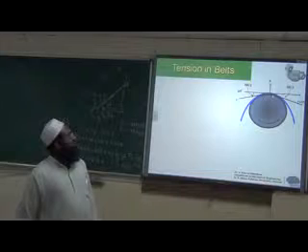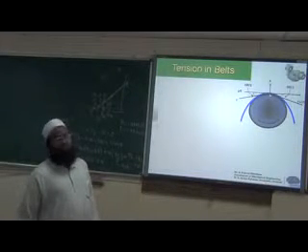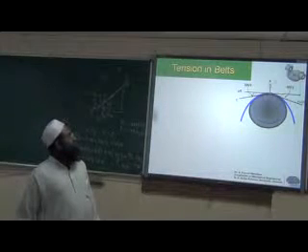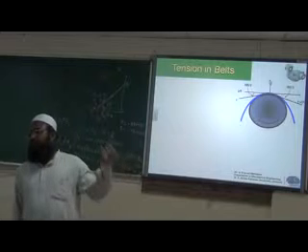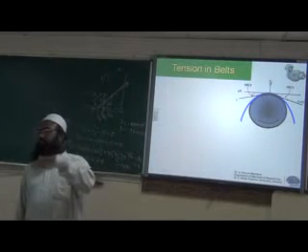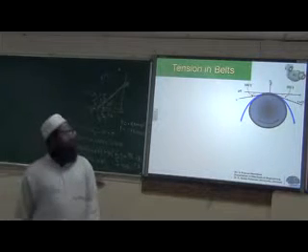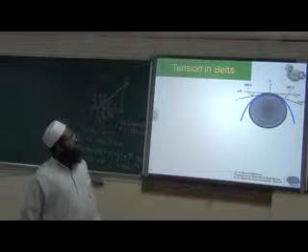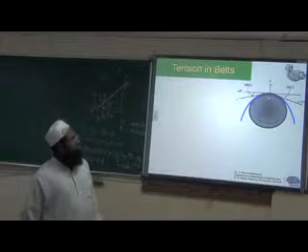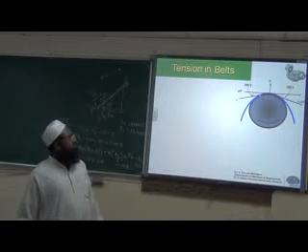At the contact point, similar to your frictional block, you will have a normal reaction R, related by the coefficient of friction mu between the belt and pulley material, giving mu R. This is the frictional force. The frictional force acts in this direction because the pulley rotates in this direction.